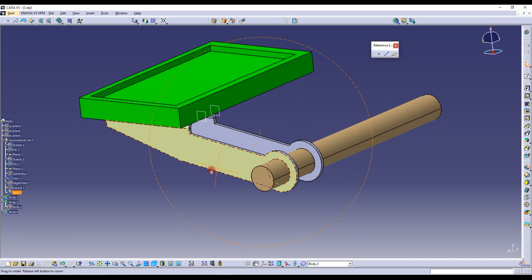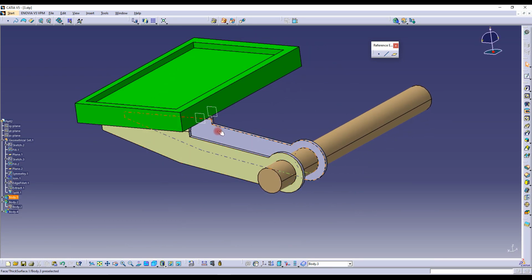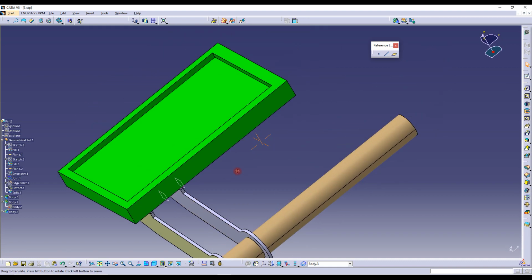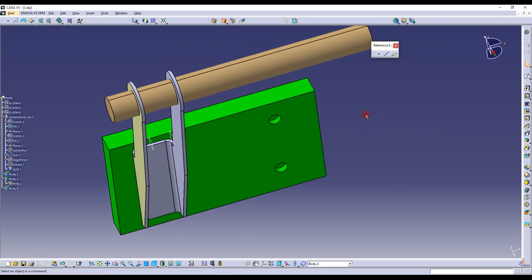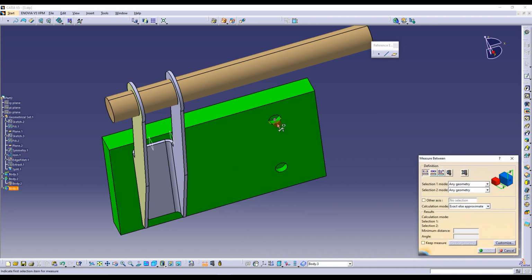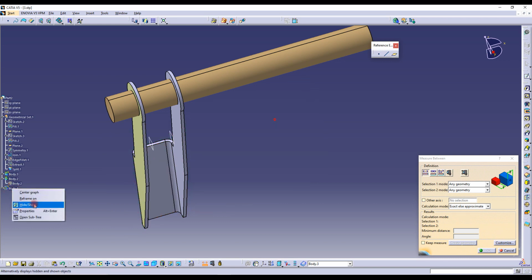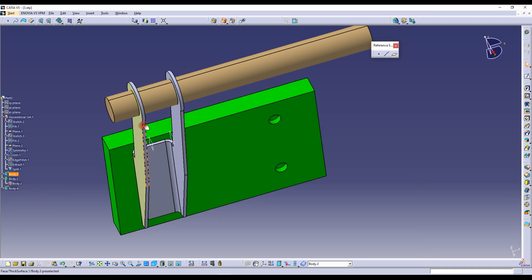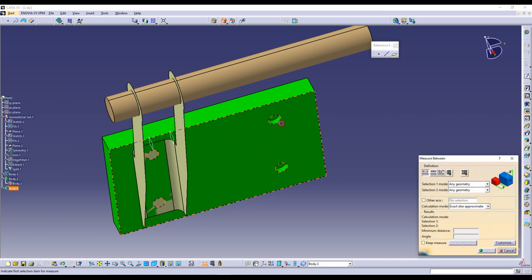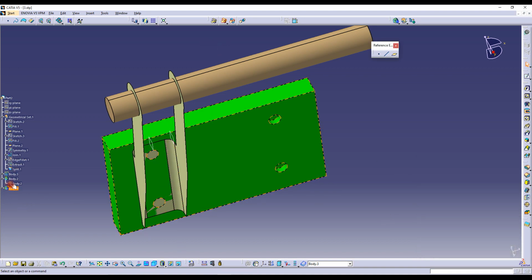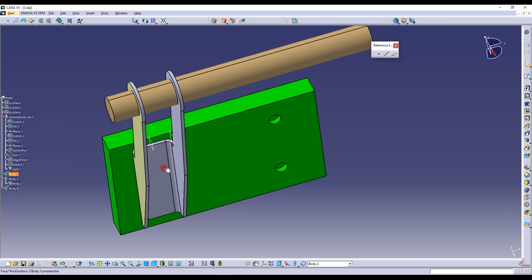Now we need to just give the fillets to make sure that there are no sharp corners. And this same bracket can be moved to the other position. So if you just calculate the distance between this center, we hide the bracket for now. So if we hide this bracket, and if we are just finding the distance between this center to this center, so 100 mm. So 100 mm, this body has to be replicated and moved 100 mm to position it on the other side. So this same part will be used for mounting these two holes as well.